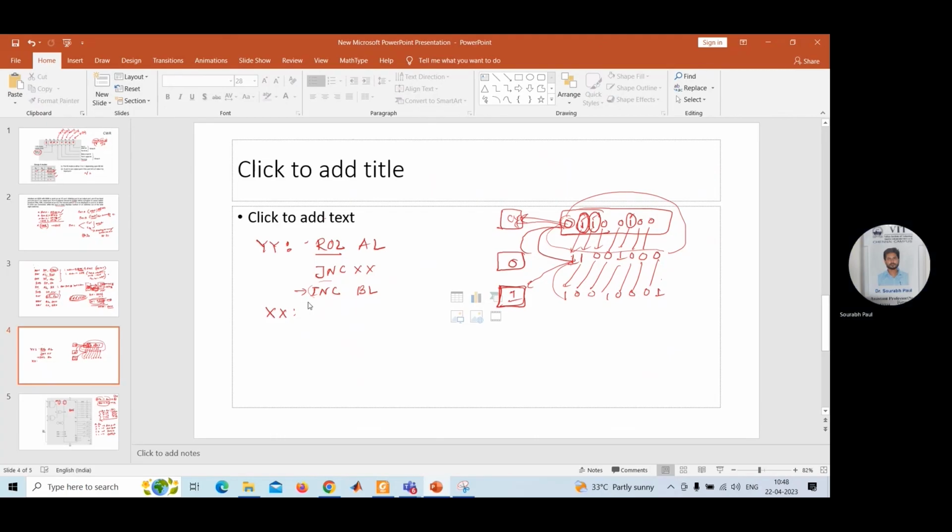As you have done one rotation, what you need to do is decrement the content of CH. It means you have already finished one rotation, and you need to do 7 more rotations because 8 elements are there. One rotation is completed and 7 rotations remain. So how to do that? Initially my CH value was 8. I have completed one rotation, then I need to decrement the content of CH. So that's why I have written DEC CH.